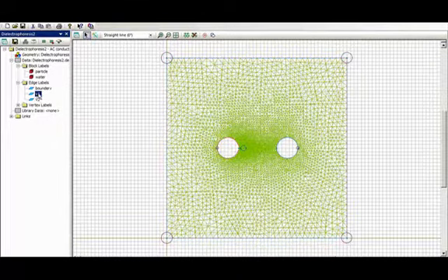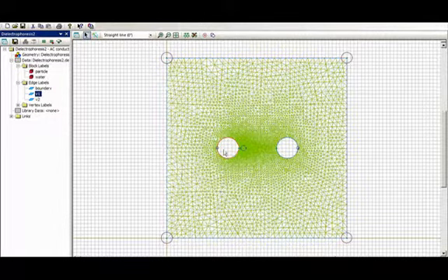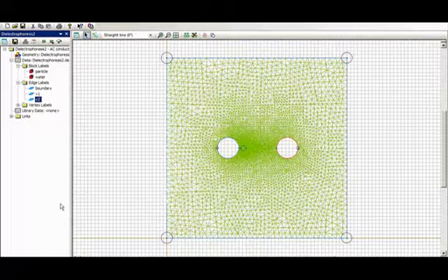The left electrode has a constant potential of -1 volt. Notice it's not really necessary to mesh the interior region of this electrode because it's at equipotential all the way around, so it's going to be at -1 volt. In the central region, we don't care about what's going on inside of the electrode here. This electrode has 1 volt. Notice that the dielectric particle is closer to the left electrode, and I'm going to go ahead and solve this problem again.